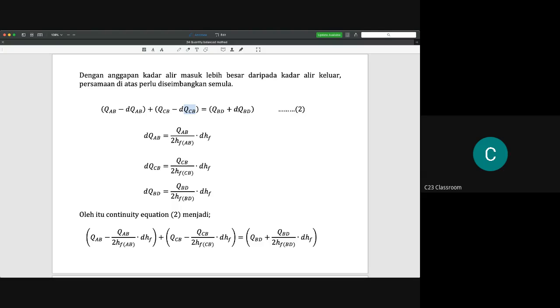It means that the amount that you add to the output here is the summation of these two amounts. So we could write it as delta QBD. Please be alert that we don't just deduct with delta Q and add with delta Q, because you know that the total flow rate must be equal. So we need to add these two values and become this term.